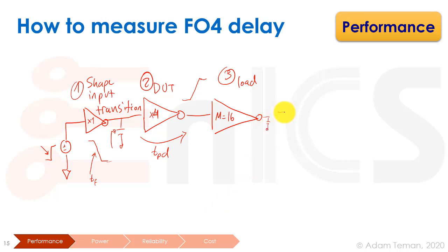And what's going to happen there is we're going to have a pretty sharp fall. And due to Miller capacitance that connects the input and output through the gate to drain type of capacitors inside the inverter, our capacitance is going to see a sharp fall over here, and it's going to make this capacitor look much bigger than it is. So that's not something we want to do.